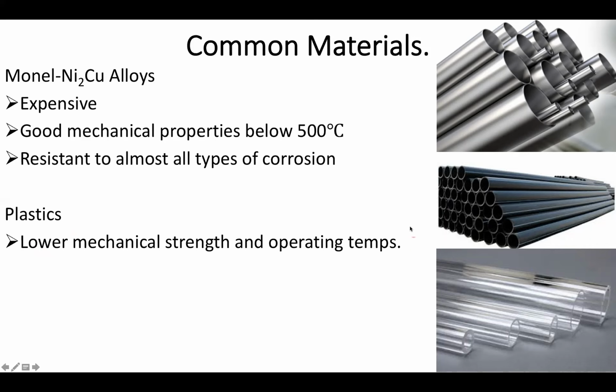However, it's also going to be fairly limited in operating temps, as most plastics will melt once we get much above 100 degrees C, and even high temperature plastics will start giving way by the time you hit 200 or 300 degrees C, which is still in the region of a lot of chemical processes.